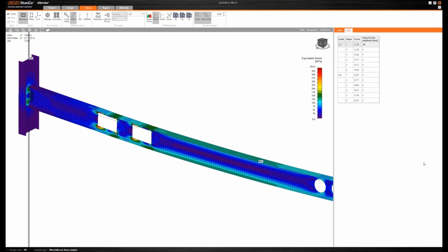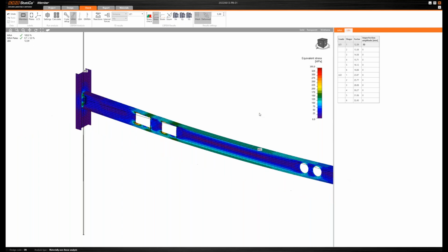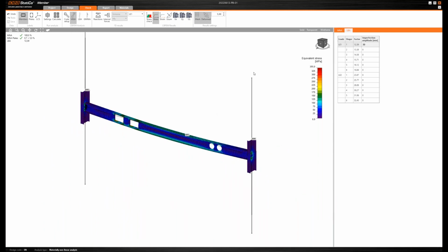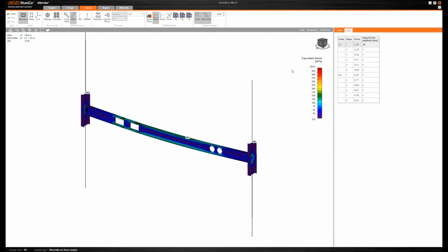Okay. Hi, is it possible to have the beam pre-cambered? There was also another comment on that, when we were talking about the challenges, that pre-cambering is also one of them. Well, if you want to have it pre-cambered, then you need to define the initial geometry pre-cambered. There is not an easy way to do this, but you can approximate it with multiple line members, let's say.